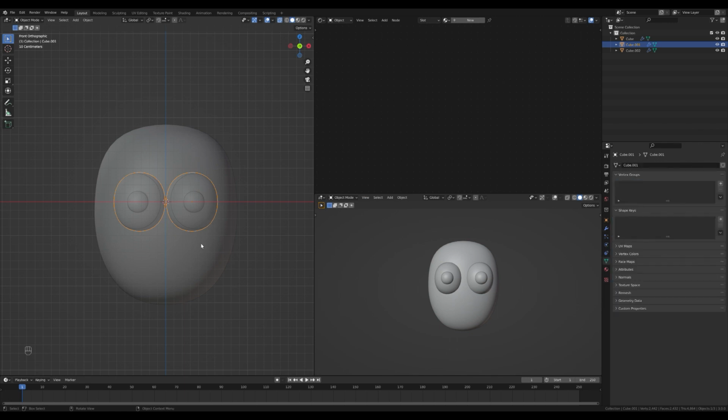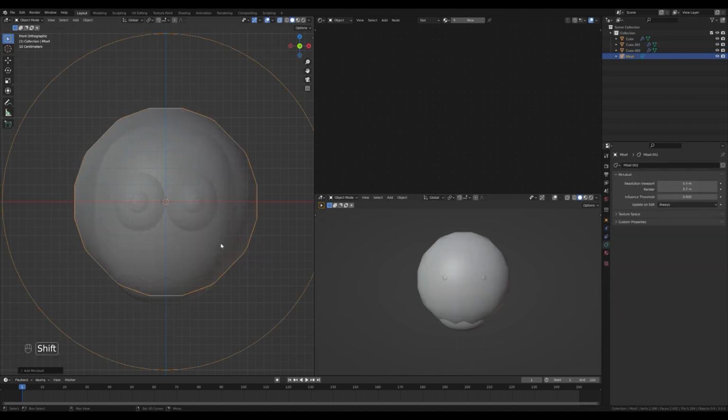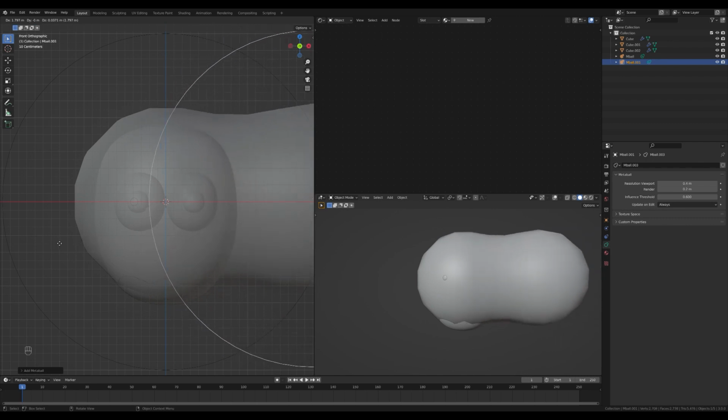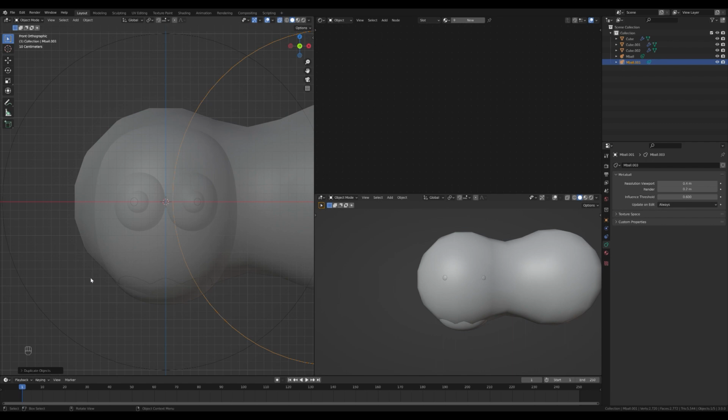We're actually going to be using a different method for this one. We're going to be using metaballs. That's right, metaballs. What's nice about metaballs, and why I like using them, is that they automatically smooth the space between any metaball. So if we add a metaball with Shift A, and then add another by duplicating it with Shift D, you can see when I move this over that they act as if they are connected to each other, like liquid. Magic! So if we use these metaballs, it will give us a pretty natural look without having to remesh. Plus I just think they're fun to play with.